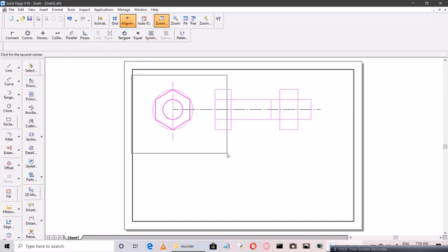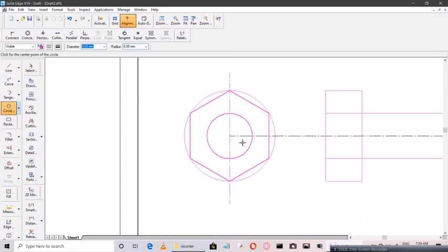So let us draw a circle here, which is equal to diameter 25. Okay. One more circle. It is a very thin circle. That is the minor diameter. Now the relation is 0.90. Now representation of this minor diameter is to be done for 3/4 portion, not more than that. The standard specification is there.